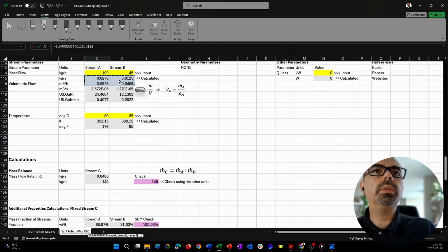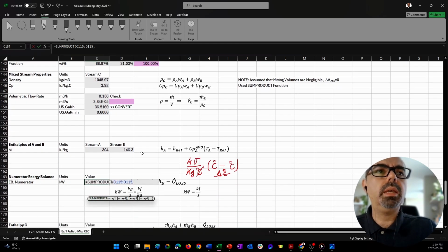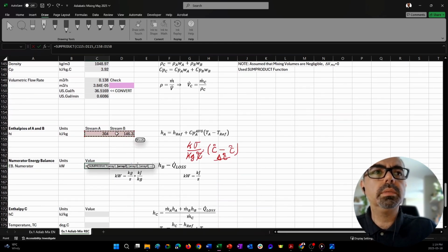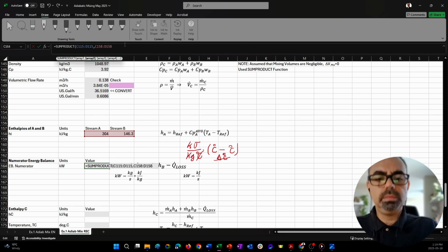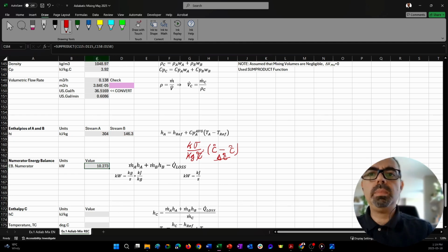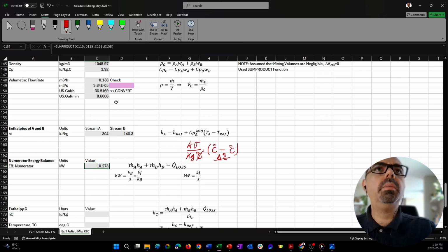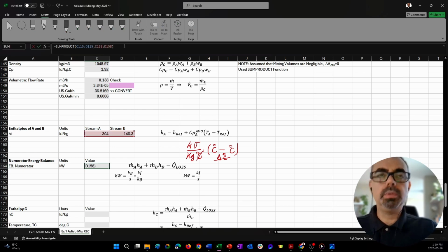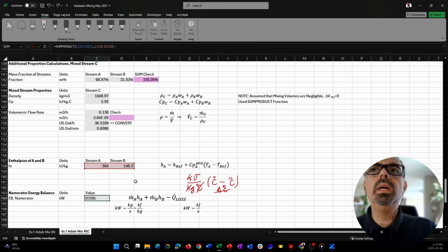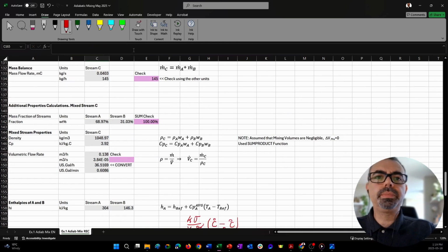So let's go here. Mass flow rates, kilograms per second, comma, enthalpies of A and B, we just evaluated. And this is the first group. And I close the bracket. I can evaluate this now. And this will give me only this portion, A and B. Now I can again come here and modify the formula, and I put minus, and I'll add the heat losses, in this case in kilowatts, just to make it consistent with the units. And that's it. That's the entire numerator of the formula.